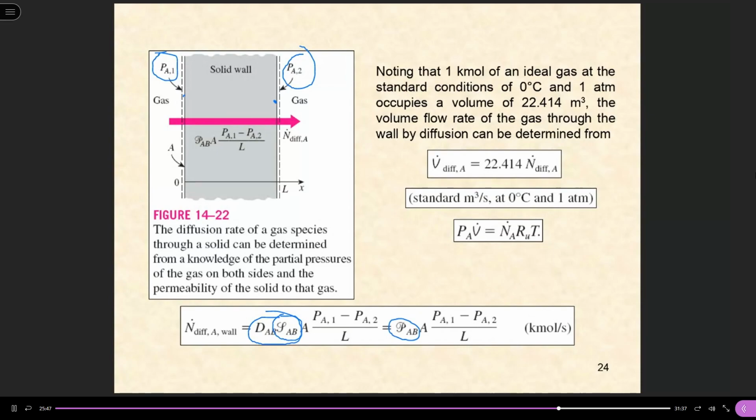You know, in heat transfer, you only have one temperature applied both to the air side and to the solid side. But in the diffusion calculation, you have to distinguish between the air side concentration and the solid side concentration, which would take a different value by taking into account solubility. Therefore, if you are familiar with heat conduction, now we are familiar with mass diffusion as well, so long as we take into account the surface specialty, that is the solubility parameter or the Henry constant. So with that, I think we have a good understanding of mass diffusion transfer.